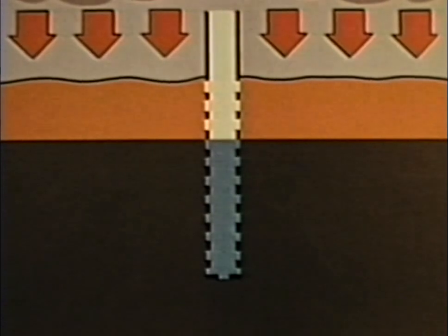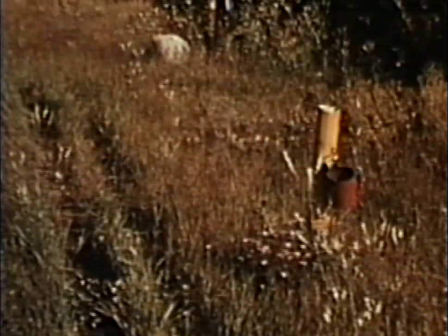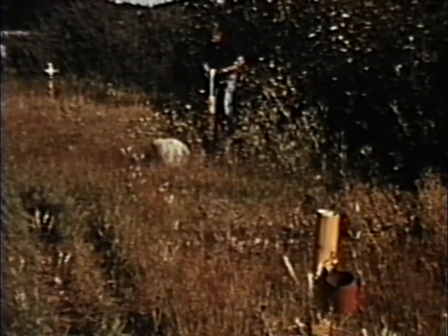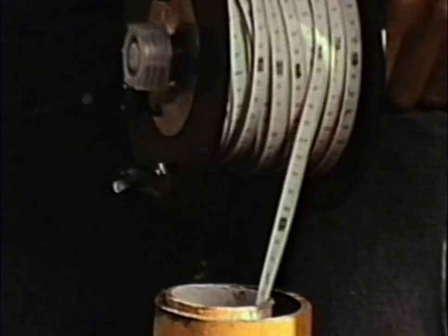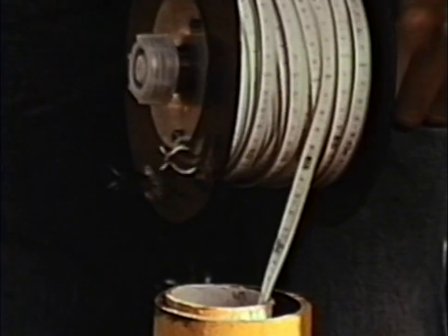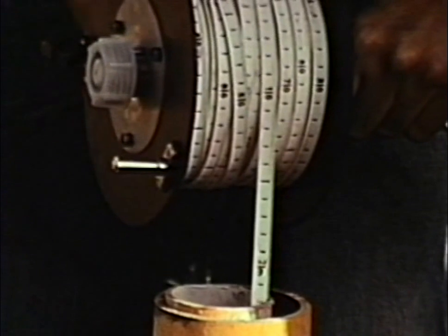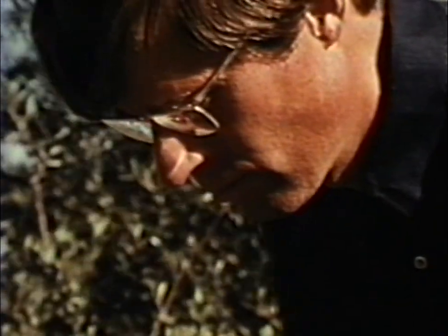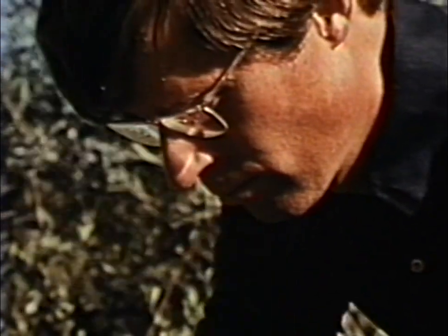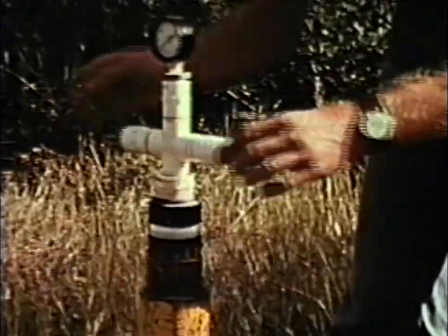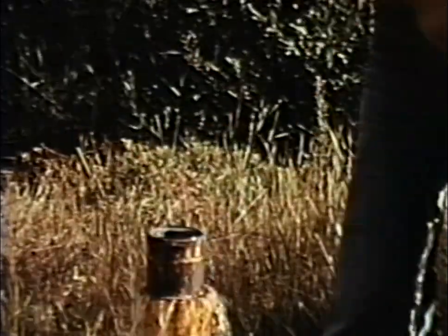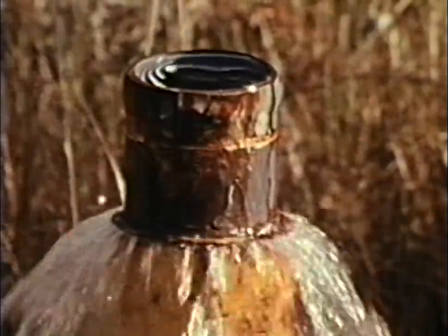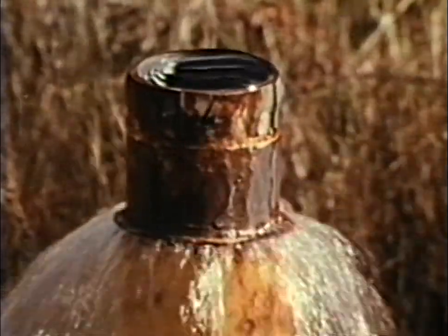The water table constantly changes its position through the seasons. To understand groundwater conditions, observation wells at different depths are needed, sometimes up to 10 or even more. Here there are 3 wells. Measurement in the shallowest well indicates that the water table is 1 meter below ground surface.